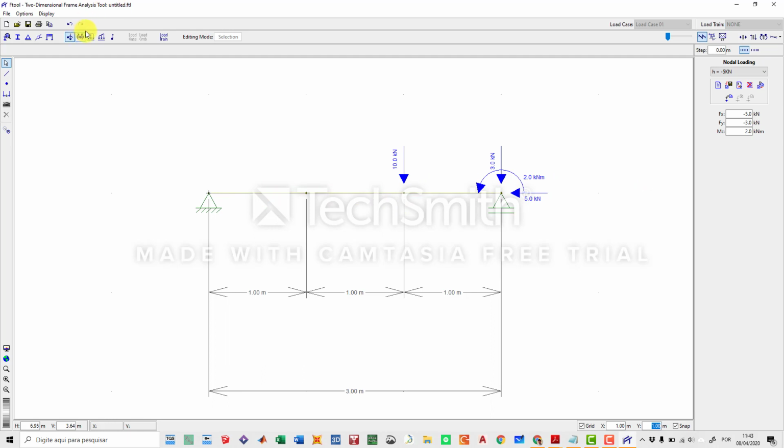And also, I can put a concentrated moment in one of the support conditions when, for example, we have a cantilever beam, and we are putting a fixed condition. You can place that as well. Here, let's put a distributed load. Here I'm going to put a load called Q equals, let's say, minus 3 kilonewtons per meter. I'm clicking done, and then I'm going to put minus 3 here and apply to that bar. That distributed load is going to show up as well. So Ftool is actually a very easy and friendly software environment where you can pretty much assess your structure for different types of loading.